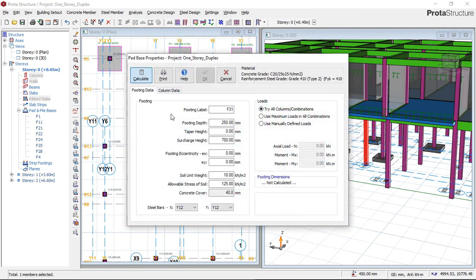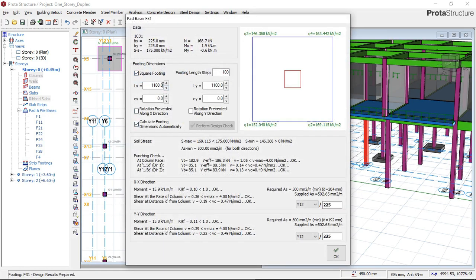Now, if you want to increase your depth of footing or your size of footing, you can also increase it here by 1, you can see it here, but don't decrease because there will be failure. So just increase. You can also increase if you want to have a uniform value, but your design will not be economical, because if it gives you 1.1 as the size of your footing and you make it 1.2, indirectly you're increasing the cost of the building for the client, and it's not economical.